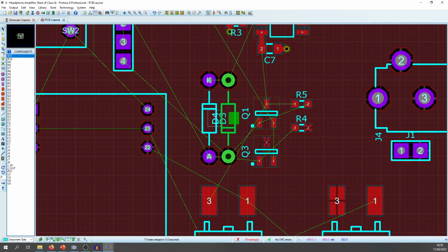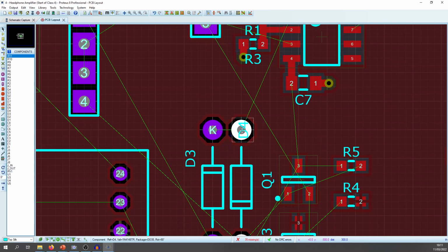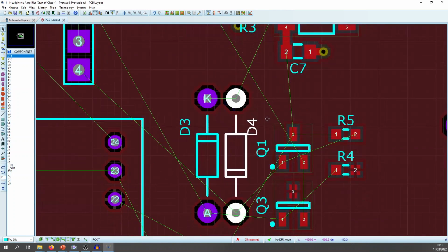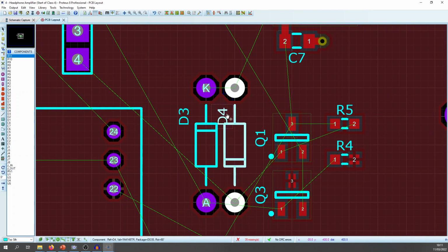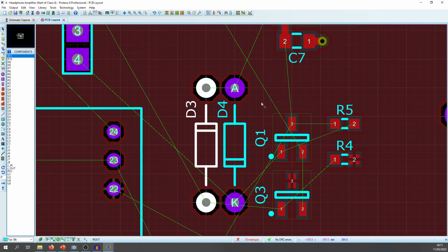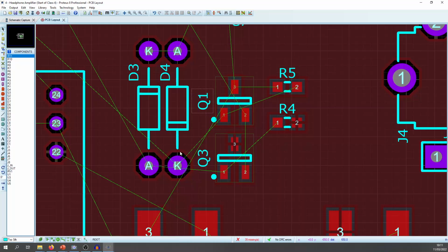Just around like that. So I'm just going to get these reference designators. When I first started doing boards, my reference designators were like here. And obviously that's a hole. You can't print into a hole. I used to be terrible for them, so I'm really strict with them now. Because you'd get a board and you'd be like, oh god, I don't know where that goes. So I'm going to connect these two together.